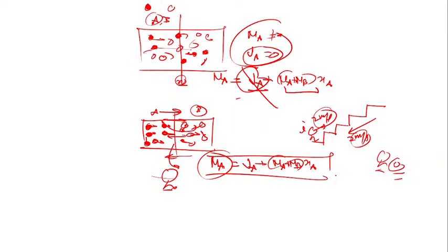Why? Because in this case Na means standing still, and it means you as an observer find Na equal to 0. It means there is no species I moving here. Why? Because both contributions are counterbalanced. Which contribution? The individual contribution is counterbalanced by the bulk contribution. Yes or no?